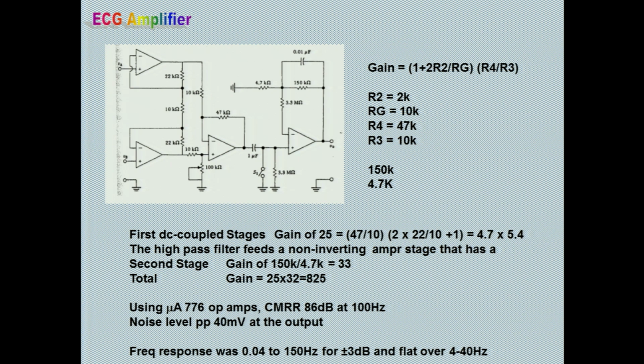Okay, everybody knows how to do the filters. Remember, the filter means that you want the critical frequency. So the value of the resistance should be equal to the impedance of the capacitor. So R equal to 1 over 2 pi Fc. So F you know, C you know, 2 you know, pi you know. So find R. And then round off the R to a normal value and then replug and make sure F is within that limit. That's how we do.